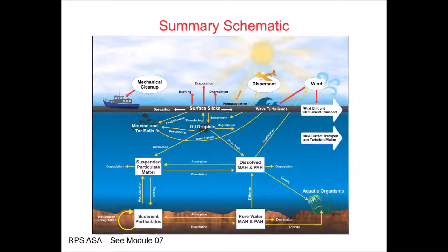So as a summary of this presentation, we've discussed that oil itself is a very complex mixture, that fate processes such as dissolution and biodegradation change the mixture composition, which then changes the properties of the oil, and so we have to have a model for the oil that can predict properties as a function of composition, and models that can predict how the composition changes over time. At the leak source, the oil is going to break up into droplets and bubbles, and these sizes are going to depend on the amount of energy and the property of the oil in terms of viscosity and interfacial tension.